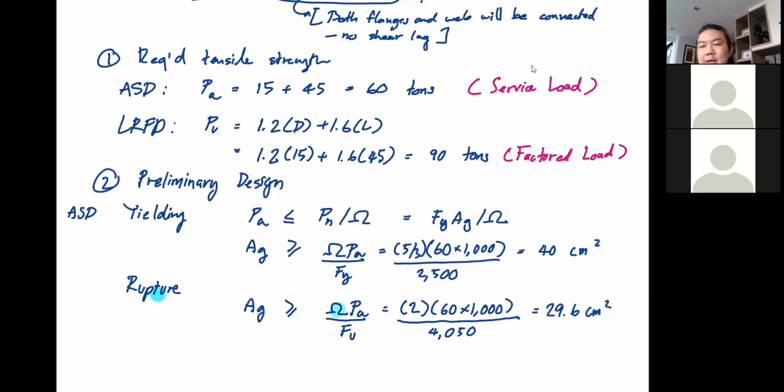That means you either reduce the strength of your structure or you increase the load by the factor of safety. It's a simple concept of trying to increase safety to the structure. No more than that. It's just that simple. Any question?